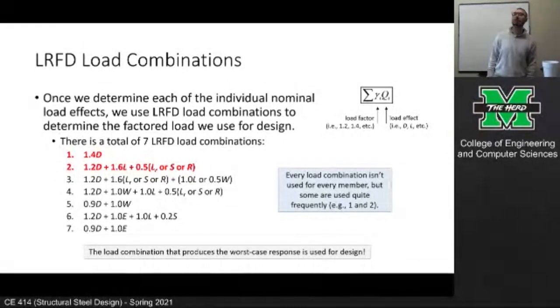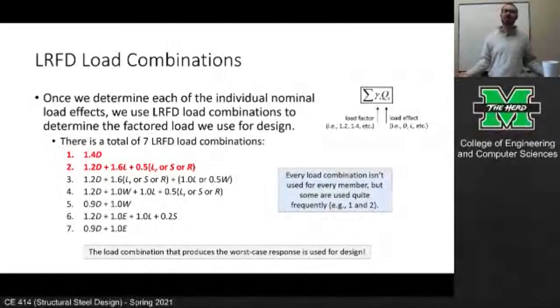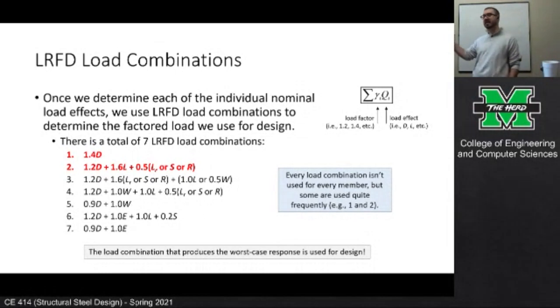Mr. Geis got it right. During construction. During construction, there's no occupancy load in the building. Now, in fairness, in real world instances, we do tend to apply a construction live load for the workers and whatnot when they're casting the deck or what have you. But in those instances, you can find that the dead load effects far exceed the live load effects because there aren't any live loads because it's being built.